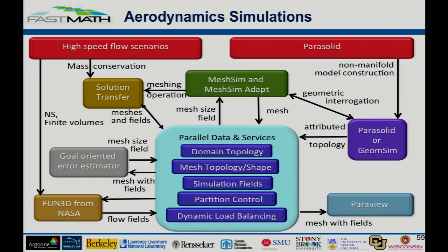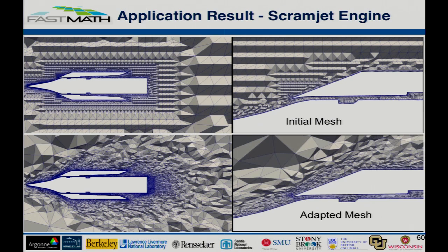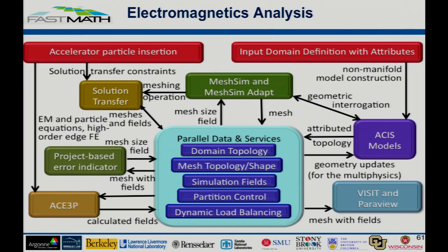Aerodynamic simulations, in this case for NASA with the Fun3D code, we're using some of the same things, although now it's a different, more sophisticated error estimator based on goal-oriented techniques, but still anisotropic. Oh, and I should mention over here, we're bringing in things in these cases always from some high-level geometric representation. As before we can interact with them, they need to be a complete geometry representation, such as a solid model. And we typically use, in our case, ParaView, but Visit and ParaView do a nice job of the visualization of these things. So in this case, just Scramjet examples.